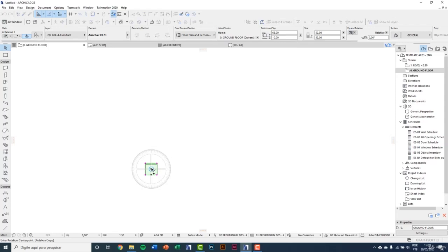Without clicking and moving the mouse, the snap guide appears. The first click is to set the central point, and the second click in the center of the chair. Moving the mouse, on each 30 degrees, Archicad makes these copies. I do a final click, and it's done.